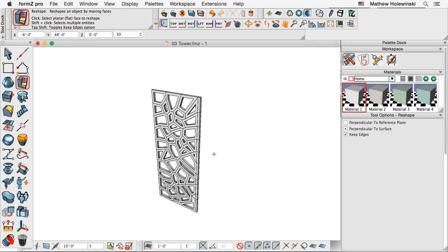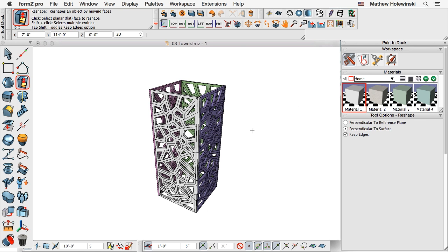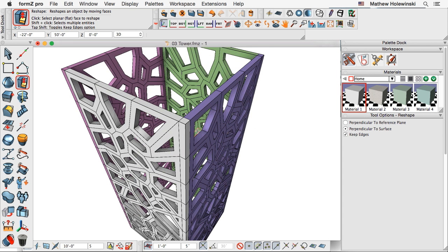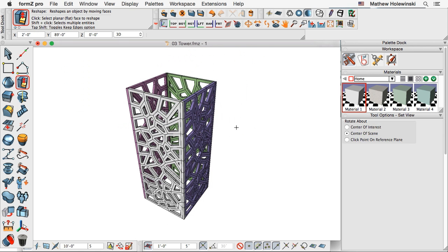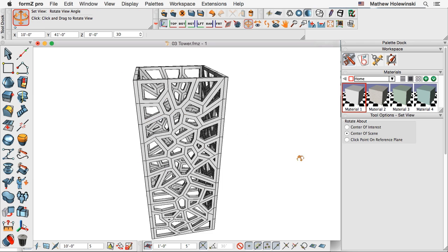All right, so then we do a rotate multi-copy again with that new piece, and then everything lines up nice and neat. Plus we have a little more material there in the corners, which is going to help us out. Now if we go and select everything, we can use the Boolean union tool to union all those pieces together. It now becomes one solid cage like we have here.